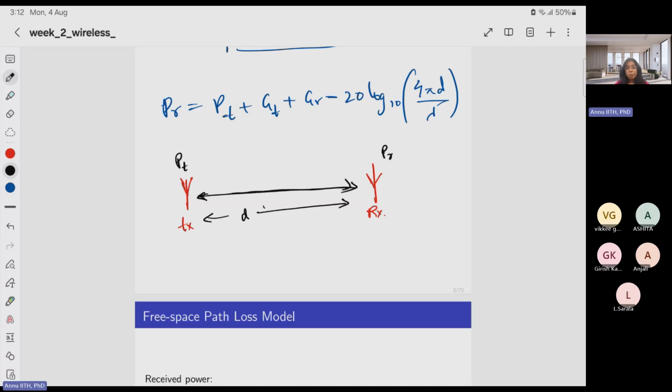Modulation converts the low baseband signal to a high frequency so that the size of the antenna reduces and we can reach a higher range. So that is why this phone can have 5 antennas. And why 5 antennas? Through MIMO technology, because we want to direct the signal in a proper way so that there is no interference and no signal loss. That is one application of modulation.